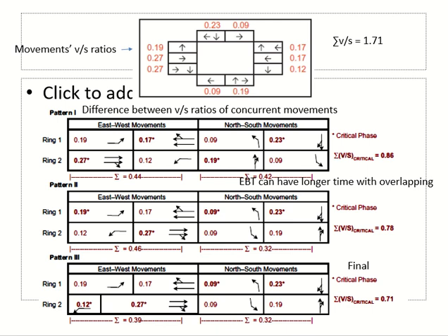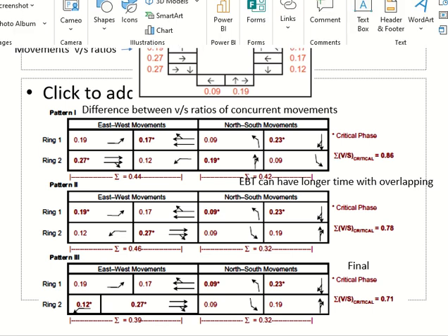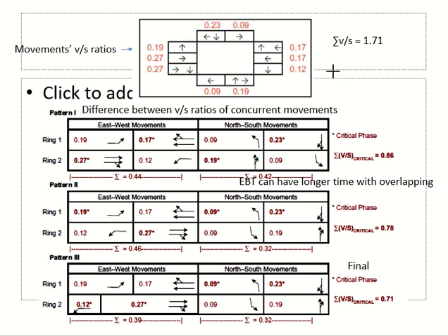Okay. So I will calculate. Now I am dealing with each phase separately. So I will calculate the effective green time for each phase separately. How do we do this? We know the total, right? Let me take the other value. So total is 84. Okay, total effective green time is 84. I have to divide this 84 into these movements.